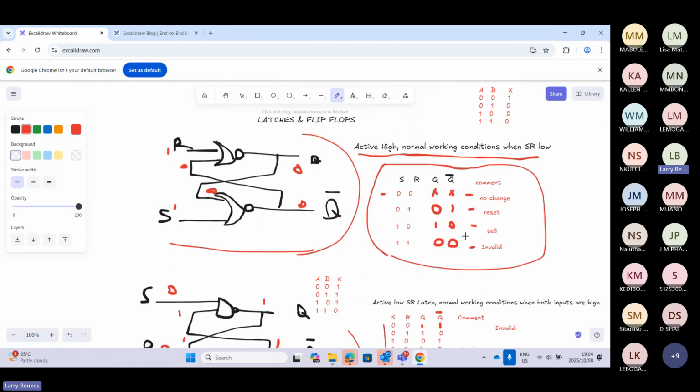To explain, guys, you don't need to stress yourself. Read this truth table. You can just say that if both inputs are low, there's no change. If R is set, for example, the circuit is in reset state. In whichever state, then you will explain this one. Then here, if both are high, it's in an invalid state, right? Yes, this is a race condition, right? It rushes to be off. So you don't really know if it's off or on, but it's literally off.